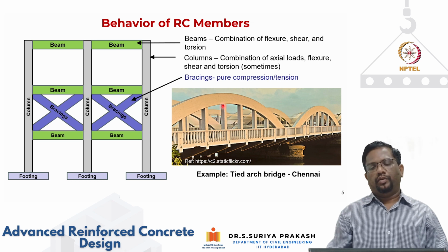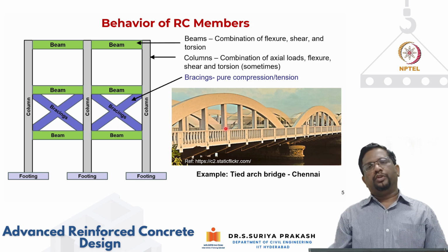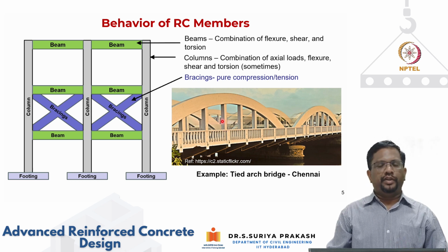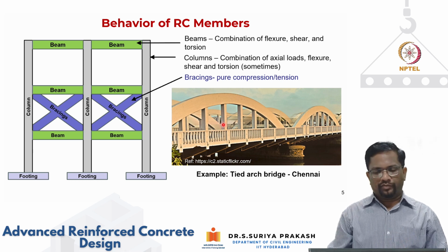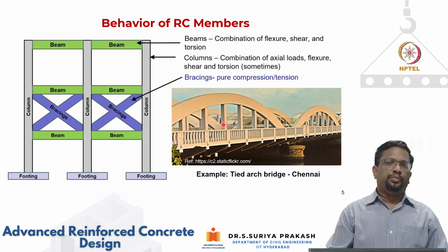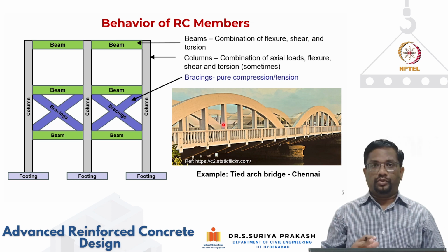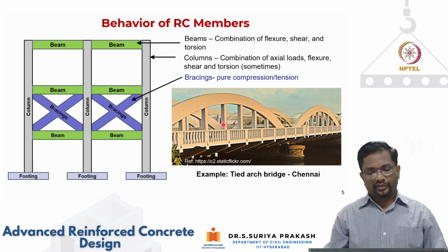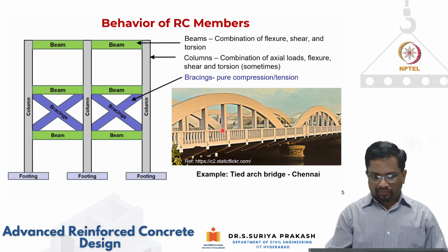Okay, but usually RC members are not very efficient in resisting tension. So we need to make sure, as we have also talked about in the last module about durability, that in tension it is not going to crack extensively and lead to corrosion and other durability issues. That aspect we need to be very careful about when you have members that are subjected to pure tension. Okay. Similarly, reinforced concrete truss systems are also sometimes used, especially in industrial factory buildings. There also sometimes you'll have tie members that will be subjected to tension.